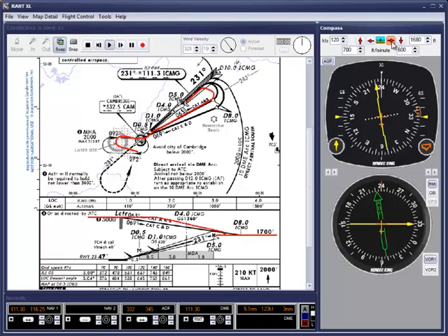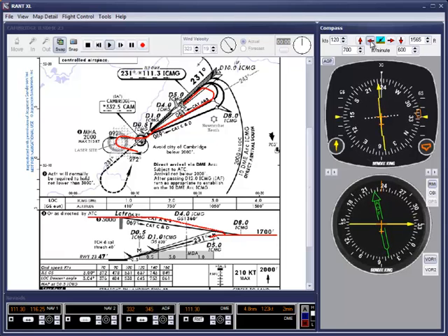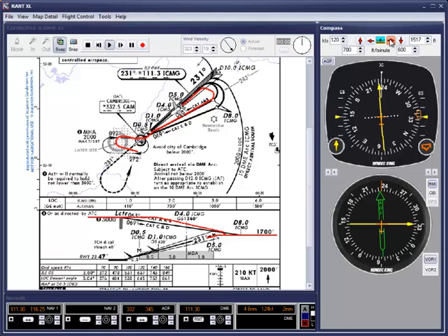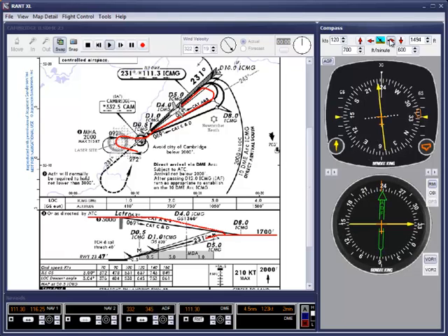Fly smoothly, making very small corrections, remembering that the wind will back and decrease as we fly down the approach. Set up the system for the go-around and always be prepared to carry it out if instructed from ATC or if the required visual references are not achieved at decision altitude, remembering that any turn must be commenced after the missed approach point.